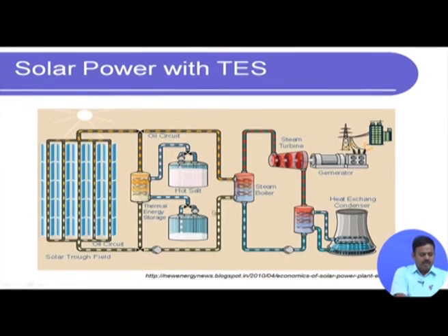So, let us now forget this part, both this branch and this hot salt and so on, whatever we are seeing, let us forget now. In a regular instance, what happens is this oil gets heated up by the sun. So, its temperature rises, it does not boil, by the way, its temperature rises and therefore, its enthalpy rises, then it flows through this loop and comes to the steam generator, where it acts as a hot fluid.